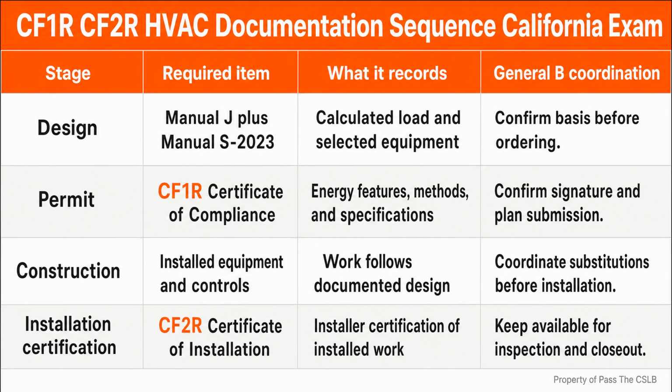The maximum is the nominal cooling capacity multiplied by 2.7 kilowatts per ton, rounded up to the closest kilowatt. For example, consider a 4-ton heat pump. 4 multiplied by 2.7 equals 10.8 kilowatts. Rounded up to the closest kilowatt, the limit is 11 kilowatts. That is a simple coordination calculation, not a substitute for the full mechanical design.